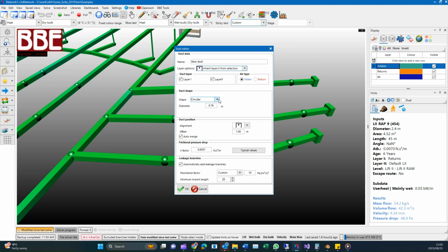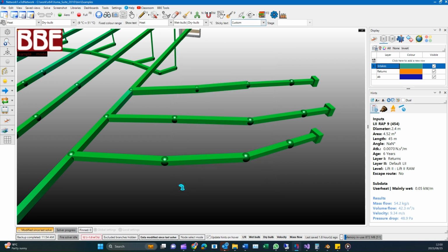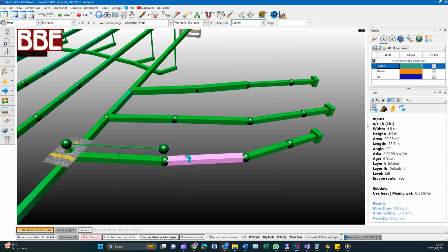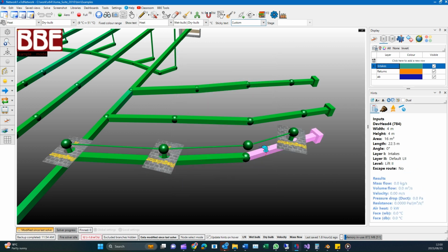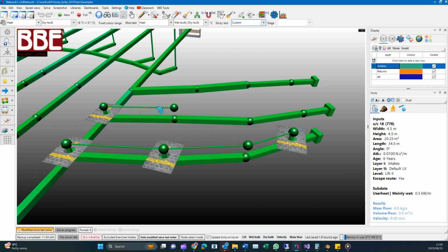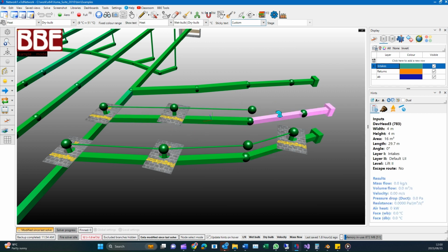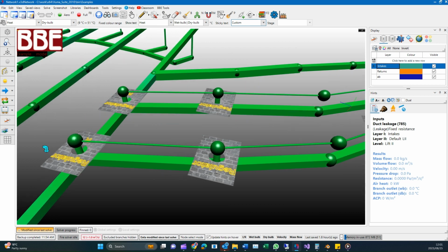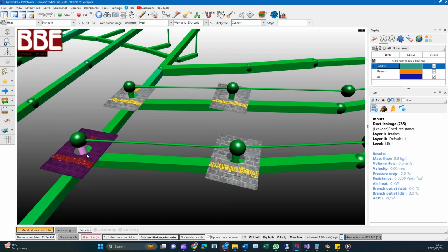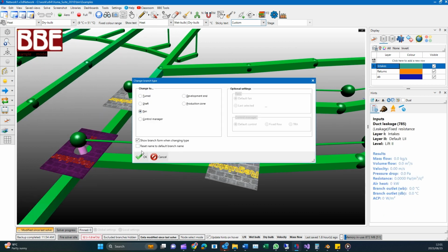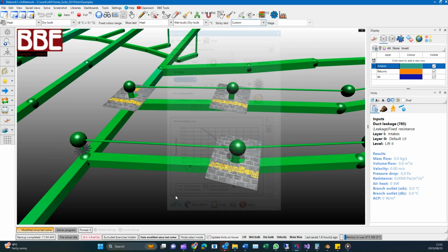On the ducting form, configure the duct's name, size, layers, friction, etc. Click on OK, and then proceed to click on all the branches where you want to add ducts. The duct will be added to the branches. You will need to change at least one of the duct branches to either a fan or fixed flow in order to force or exhaust air through the column.